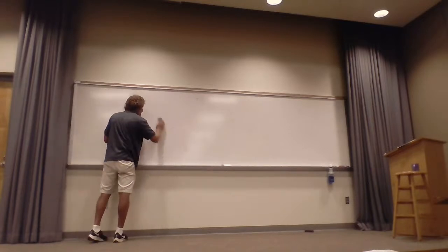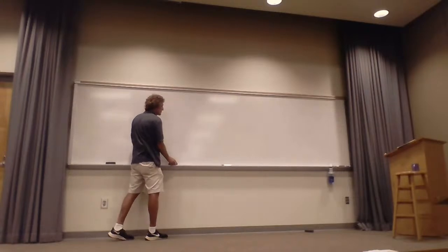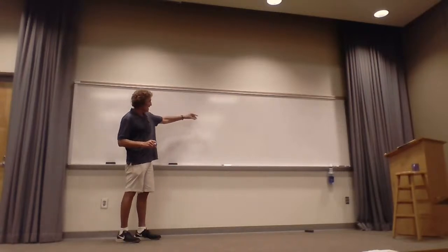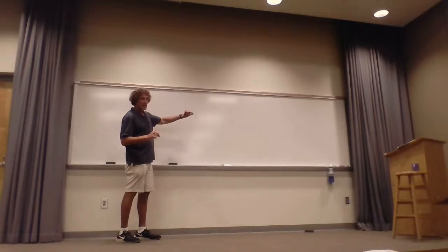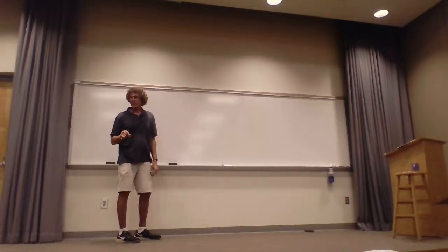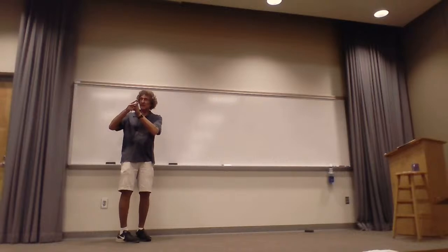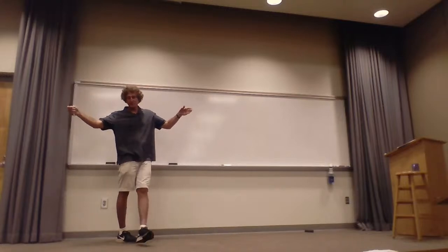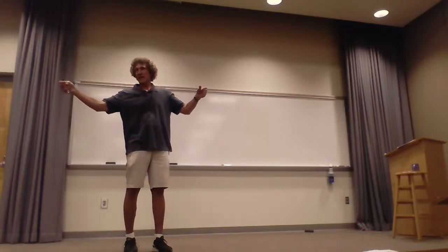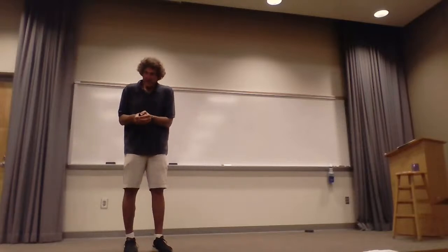Because let me just tell you this. In the real world, I may have an antenna that I mount. Usually everything's mounted on these boards with a coax line first. Right? You get a coax cable, it's cinched to the board, and then it comes in there and it's fed by a transmission line. Well, if you don't have impedance matching there, it's very bad. So how do you impedance match something where you might have a transmission line of 200 ohms characteristic impedance, and then you've got a device of like 50 plus j10, and you only have a little bit of space?